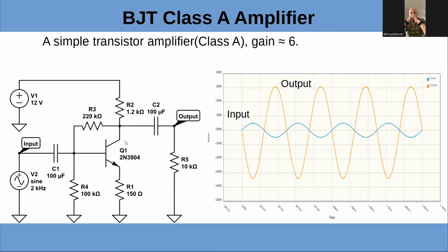And like I said, if this is 12 volts, you'd normally set this bias so with no signal, you're going to be sitting at about 6 volts at this point. So then when you put a signal in, it allows it to swing between 12 volts and 0 volts. But it's always going to be sitting at 6 with no signal.